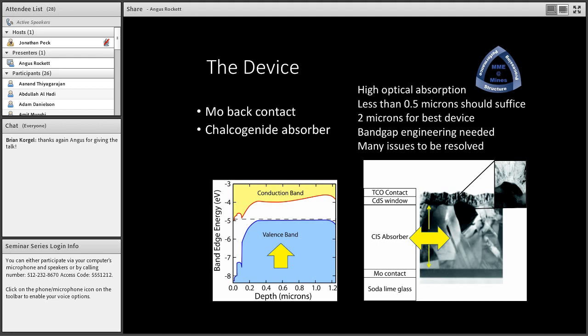Presumably it's because you're establishing growth conditions, getting the grain sizes established, getting rid of some defects, and optimizing the general structure of the crystals in the absorber material. We can hope that ultimately devices will be less than a micron thick when finally optimized,